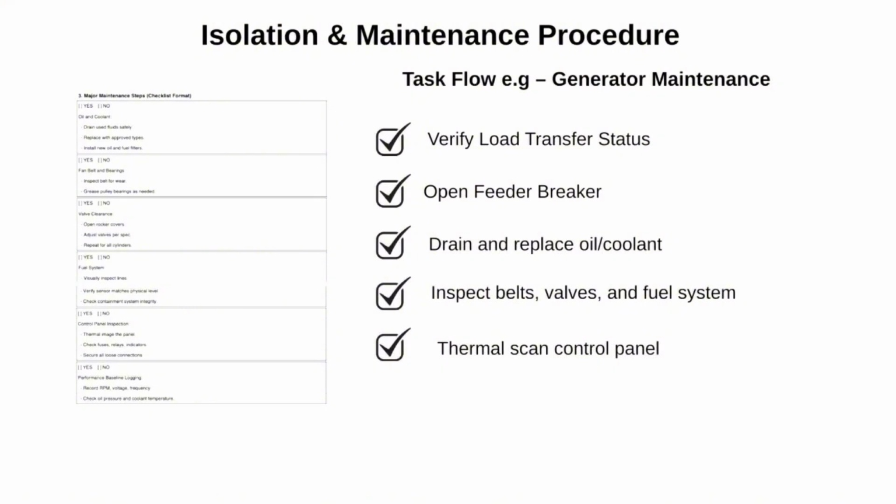Thermal scan the control panel. This one's all about predictive maintenance. A thermal camera can help you spot overheating relays, loose connections, or stressed components. In case you haven't used one, it's as simple as pointing and scanning, but the MOP should say what to scan and what's considered abnormal.